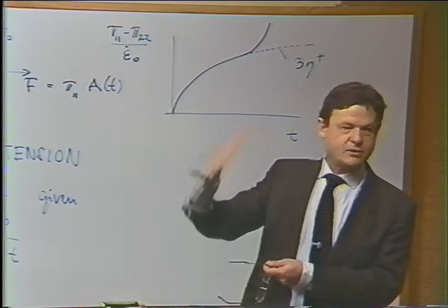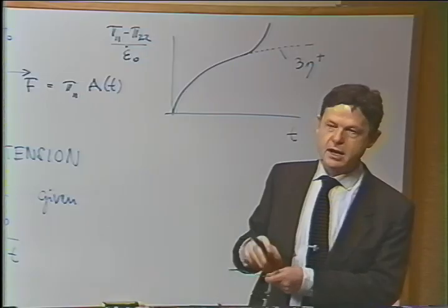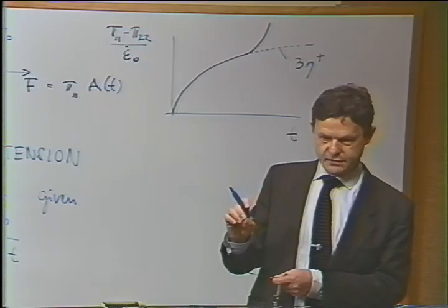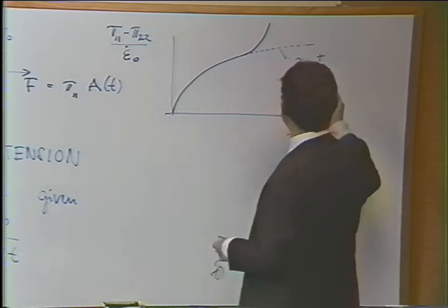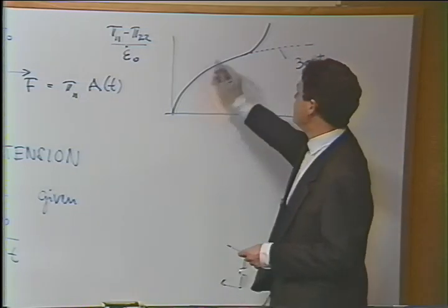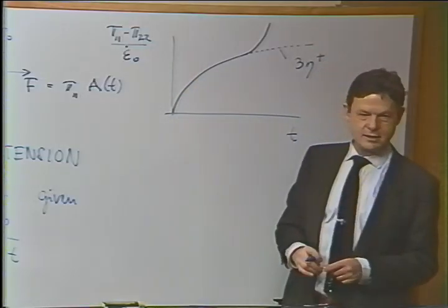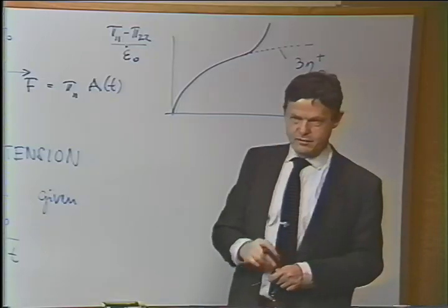And if you divide that, you have a viscosity as a function of time for that material element. Now, in the limit of low rates of deformation, where you don't have the overshoot, then you measure this function, and 3 times that function is now given in extensional flow. And the factor 3 comes simply from the geometry.